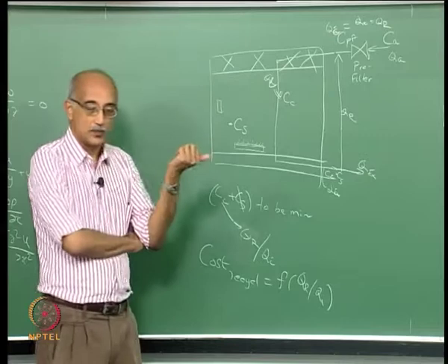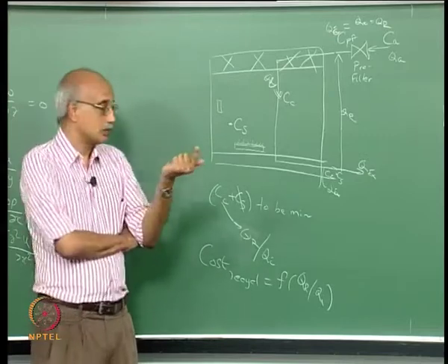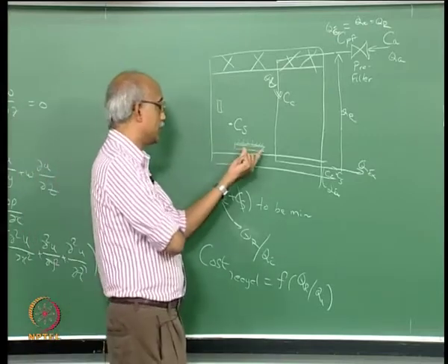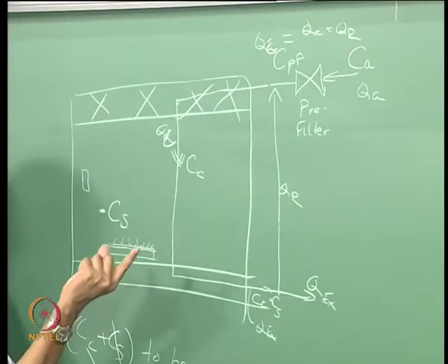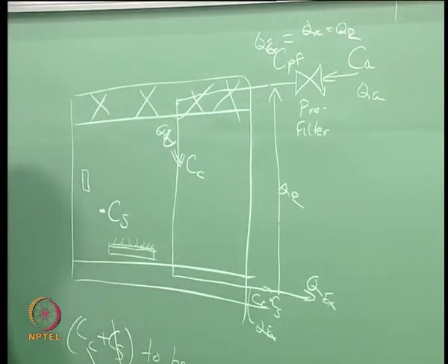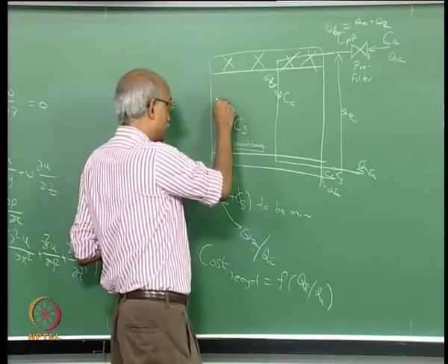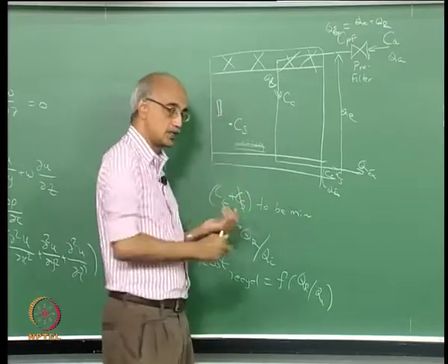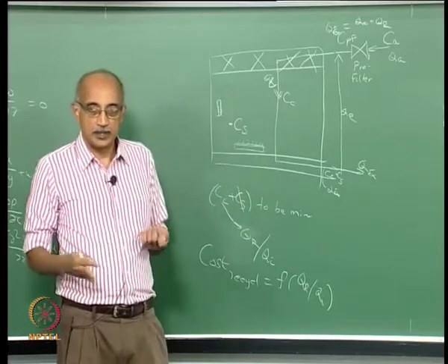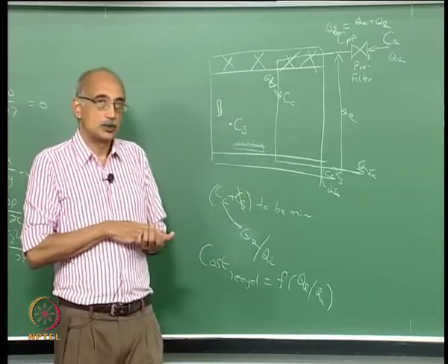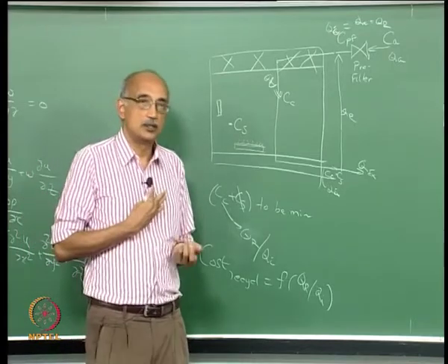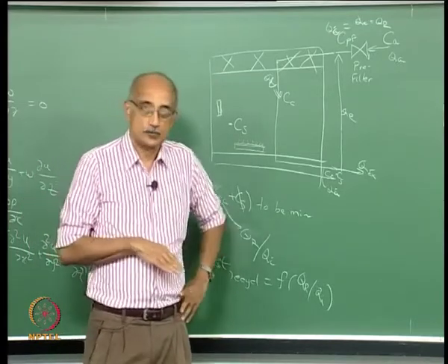So, location is important. Orientation is important because if you orient the surface horizontally in this example, the rate of deposition is going to be very high because stagnation flow can develop over the wafer, whereas if you locate it in a configuration where it's parallel to flow, then deposition due to impaction, for example, will be distinctly reduced.